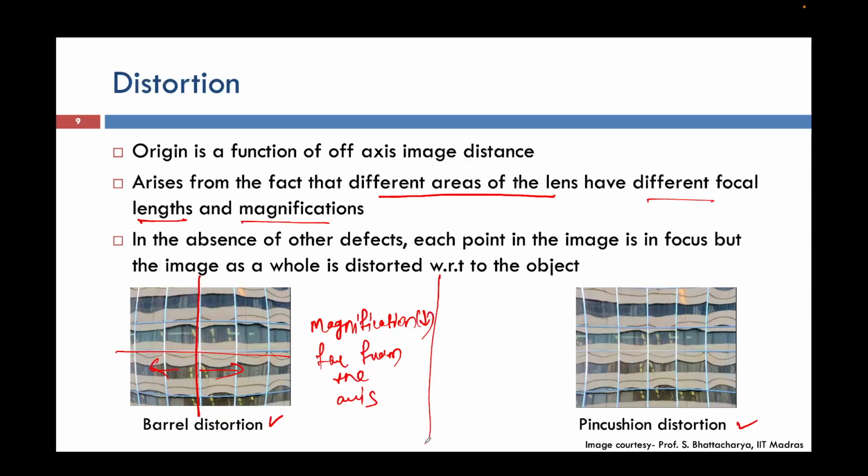And if you remember the condition for buckling, when we apply some load to a certain material, there is also a condition for barreling. Barreling means that when you are compressing something mechanically, loading it, the top and bottom portions stay in their respective positions, while radially the material starts to grow.